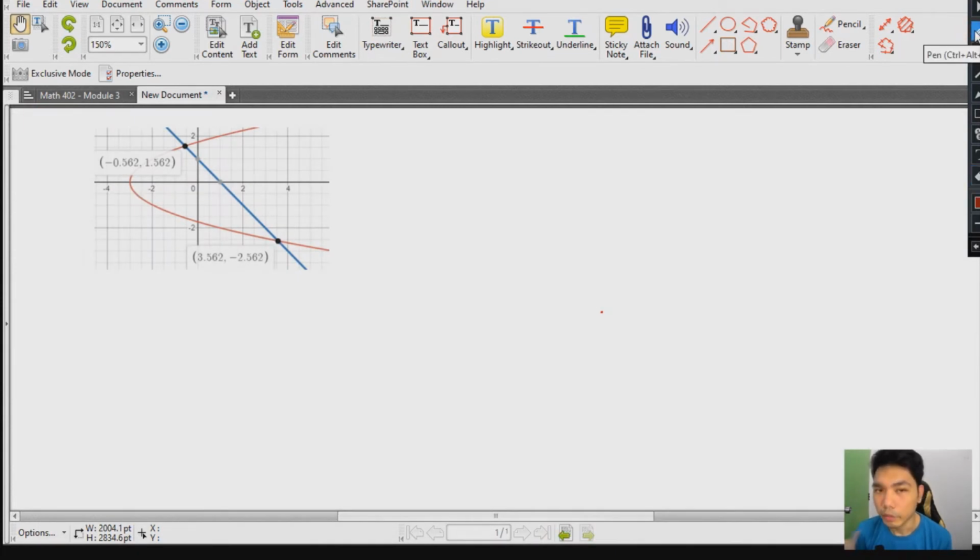And remember, we'll be utilizing the concept from number 1 na if you have the mass and you have the center of the mass, you multiply it to the center of the mass and then divide it by the total masses of the objects that you have. So we have here the first strip, and then this is the second strip. And remember, we need to determine the mga points na kailangan natin. So remember, in this case, since this is the farthest one, the critical point here is at -3.